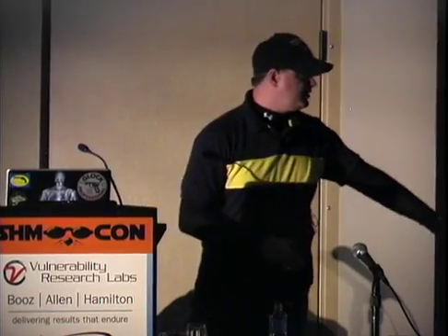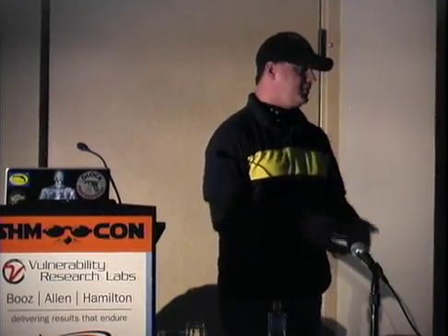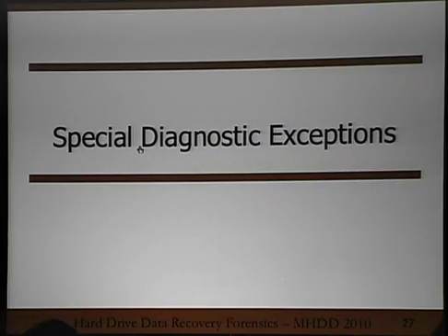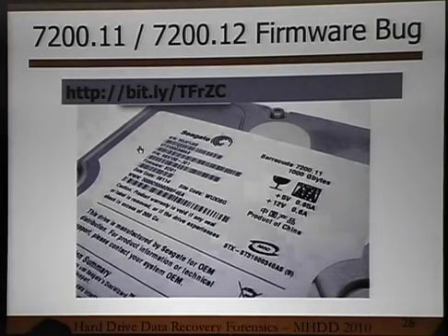So you already know right away if I'm able to read some SMART data, I may have made it further than, it doesn't matter if I'm reading user data, I may have actually been able to tell that the drive initialized correctly and it made it through this POST routine because it will be one of the later things that actually happens. There are a few exceptions. Almost all of these exceptions have basically happened in the last year, year and a half. So I'm going to talk about these really quick before we go to the diagnostics component.